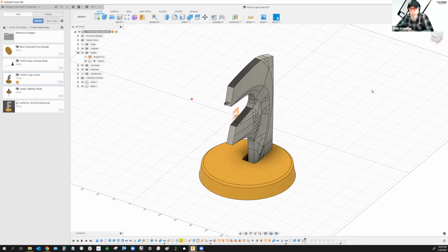If they were to use XREF, the whole assembly would come in, and they'd have to break the link and break it up. Whereas by using Derive, they can get just the panel bodies themselves and create a cut job. Is that a little closer to what you're thinking? Absolutely, thank you. That answers it.